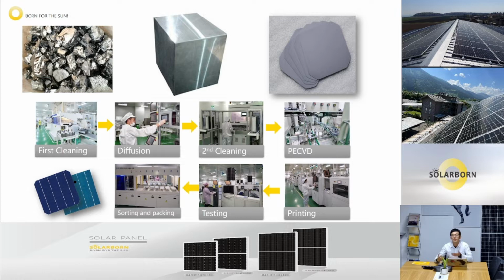Silicon, where we get the silicon materials and come to the ingot. Ingot, we get and cut the ingot to get the mono or poly wafer, and then we will go to the solar cell production workshop to have some process from wafer to solar cell. First process we do is the first cleaning.